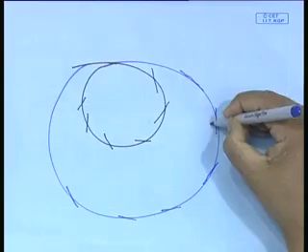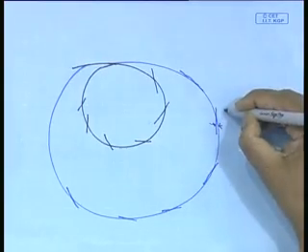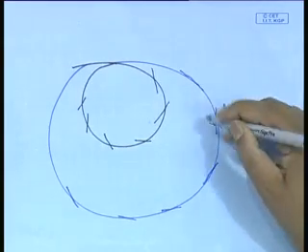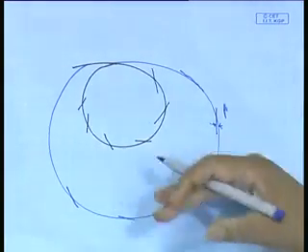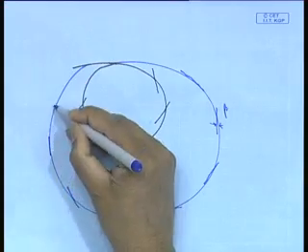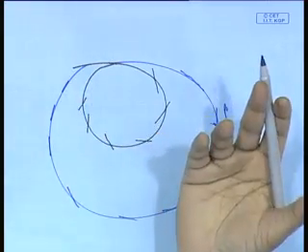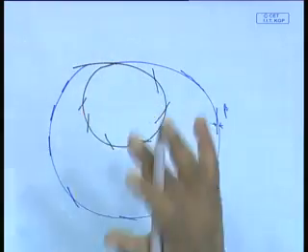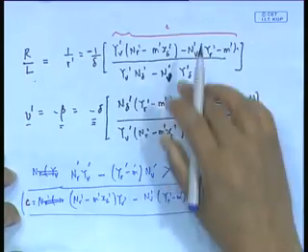In fact, you will find interestingly that if the radius is made infinity, then beta becomes 0, which means beta can only become 0 when the ship goes on a straight line, because R infinity is a straight line. But if you were to turn, you have to have a beta. The point is well taken: you cannot have a ship turning exactly like this. You just cannot. The existence of beta is a necessary condition for a ship to turn. You can see it from there. These are all interesting consequences.